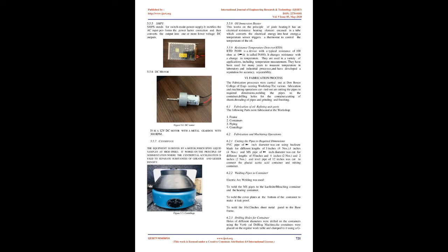5.5.4 Relays. Relays are switches that open or close electromechanically or electronically. It's a 5V relay, with one normally open and one normally closed contact. The control pins have a pull-down circuit to prevent floating relay malfunction. Figure 5.4, Relays. 5.5.5 SMPS. SMPS stands for Switch Mode Power Supply. It rectifies the AC input, performs the power factor correction, and then converts the output into one or more lower voltage DC outputs. 5.5.6 DC motor. Figure 5.6, DC motor. It is a 12V DC motor with a metal gearbox with 300 RPM.